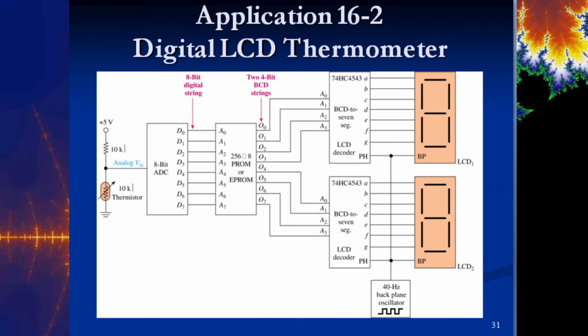So here's a good example of where this would come in handy. We know from our previous discussion on analog to digital converters that a thermistor is a nonlinear device. So every step up that you're going to count in binary, or every count in decimal for that matter, is not going to be linear, and it's not going to be proportional for each step. So that's a problem. As we know, the thermistor is going to change as the temperature changes. And again, it's nonlinear, but as that resistance changes, it's going to change the voltage that drops across it in this small little voltage divider here.